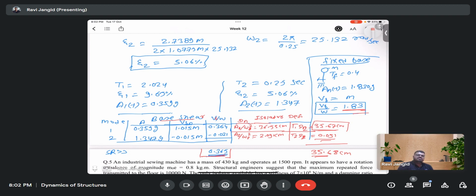And we have to do the forced analysis of the multi-degree-of-freedom system to find out the modal frequencies? Yes, you can do that. On the right-hand side will be whatever ground motion I am giving, like 100 hertz, 200 hertz? You can give a range of frequency from 0 to 50 hertz, or 0 to 30 hertz, and corresponding to that you will get a Fourier curve or something, depending on the data acquisition system you have. From that you will easily get your modal frequencies.